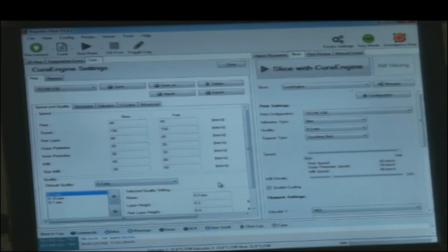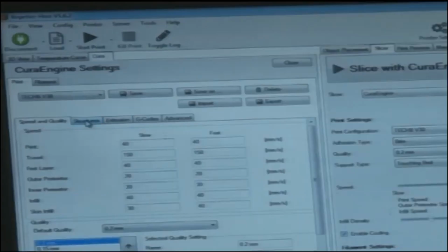Sometimes we find that our dimension or our profile shape is important. If quality is not very important and only the profile shape matters, then we can go for rapid printing, that is 0.2 mm. Sometimes we feel that the size and dimension as well as the quality need to be higher, so we can keep 0.1 mm layer thickness.